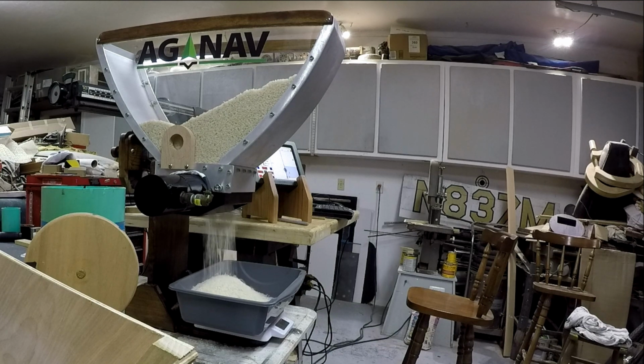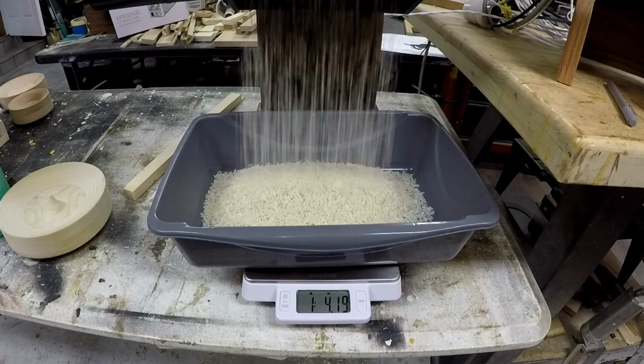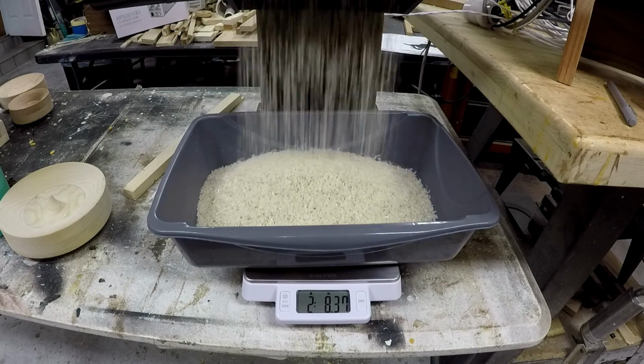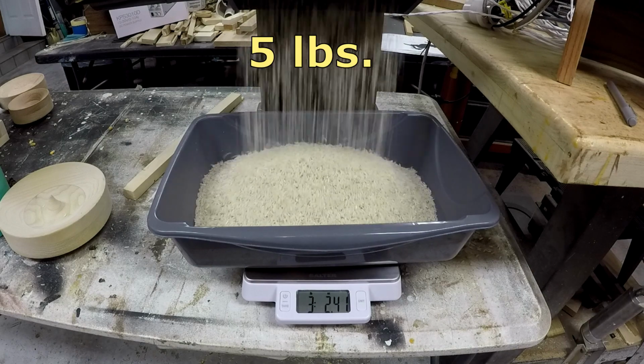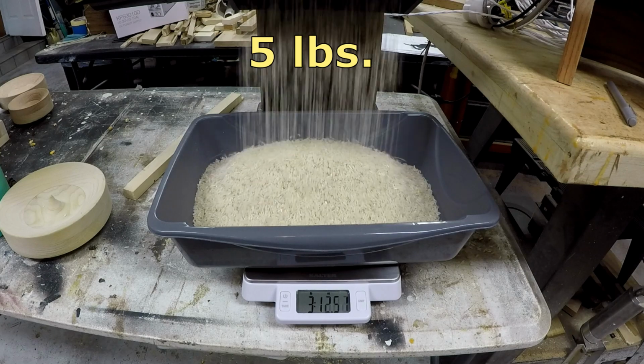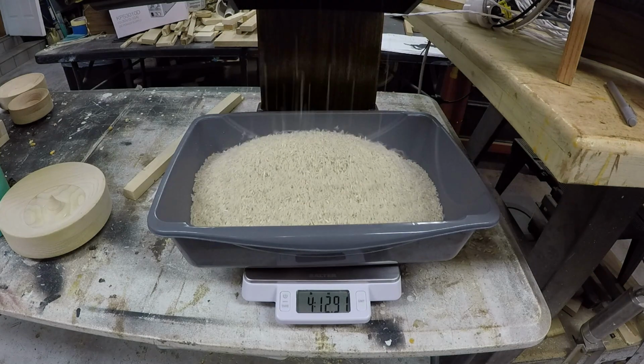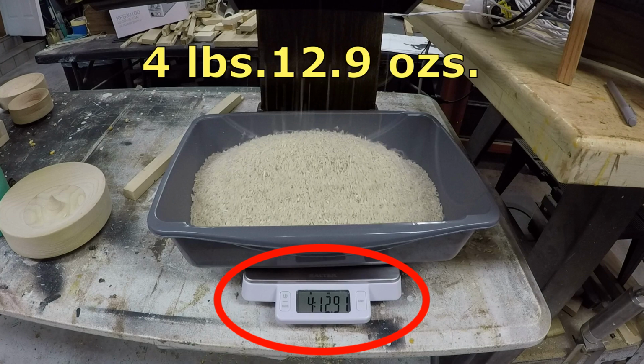Here's a video. I'm collecting the granulars in a bin, and I bought a kitchen scale, and it's 5 pounds per acre, and I'm spraying a 2-acre run. So my weight should come out to be about 5 pounds. And here we have 4 pounds 13 ounces, which is pretty close.